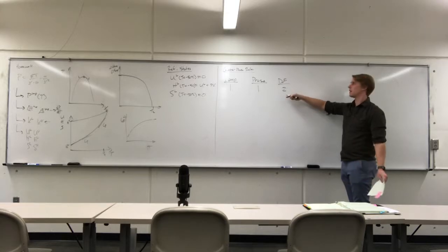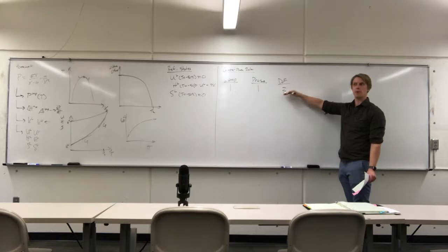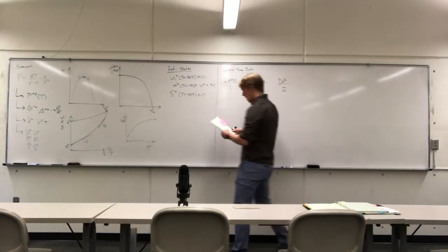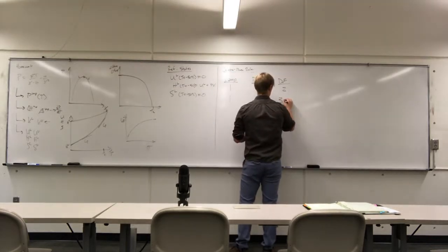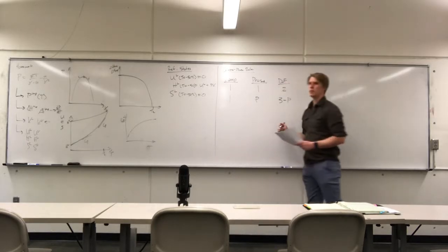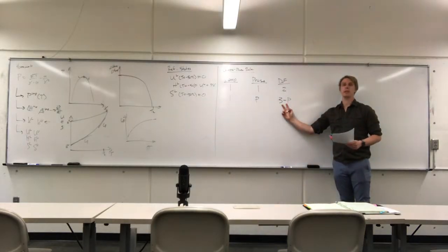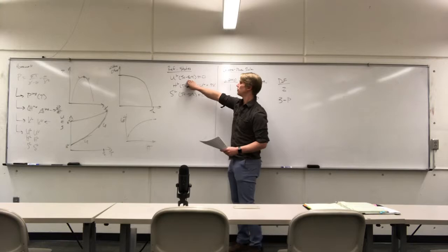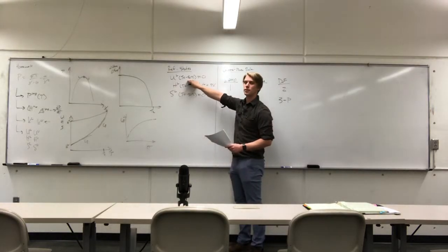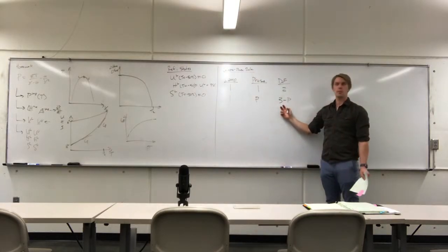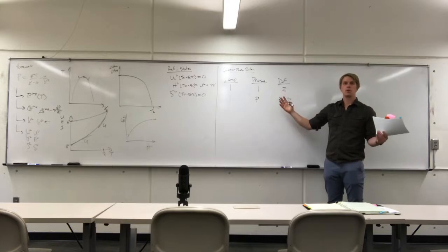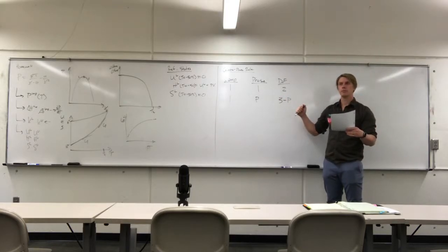All of thermo is built on this assumption as well, that we can fully describe a macroscopic fluid by 2 properties. Now, if I have one component with many phases, we showed earlier that our degrees of freedom are going to be 3 minus P. So if I have a 2-phase system, like liquid-vapor equilibrium, that means I only have 1 degree of freedom. Consequently, I only had to define one condition saying this is the saturated liquid internal energy. If I have 3 phases at the triple point, I have 0 degrees of freedom. I have no choice where the triple point is. It's just locked in place.